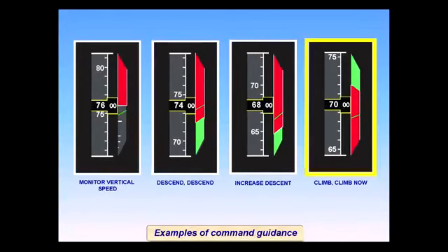When vertical rate commands are given, the pilot has 5 seconds to react and begin a climb or descent at the rate recommended by the green bar on the tape. Resolution advisories may be corrective, requiring an evasive vertical maneuver to maintain safe separation, or preventive, in which case no change in vertical speed is recommended. In some cases, the original command must be increased or even reversed. The reaction to increased or reversed commands must be made within 2.5 seconds to ensure the desired separation.